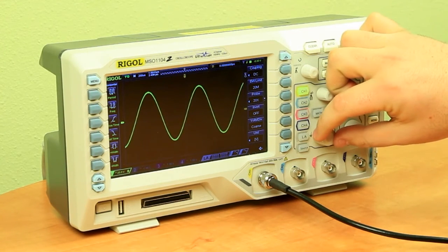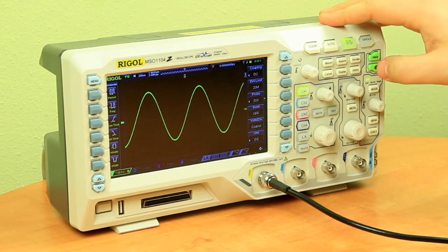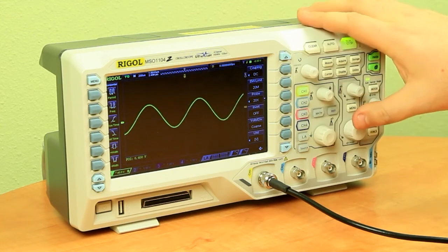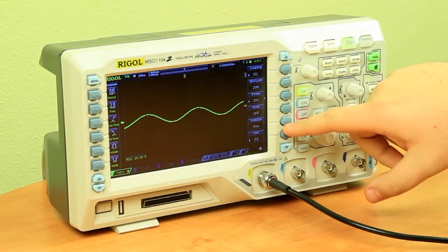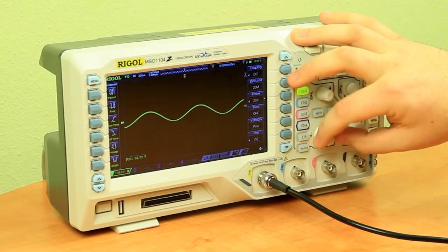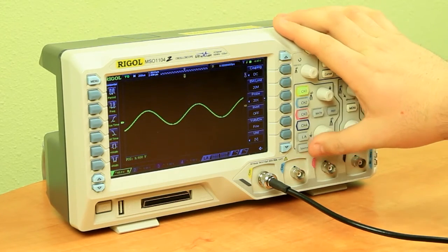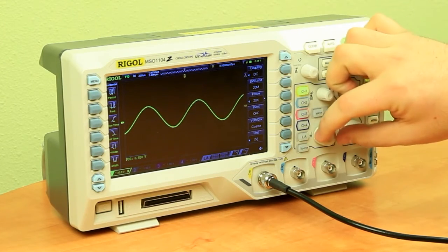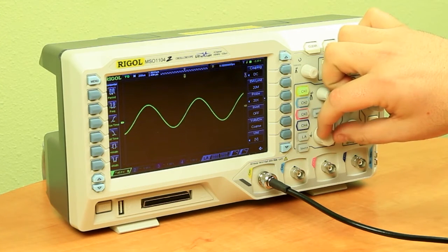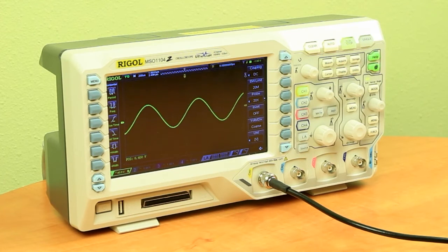Another aspect is we can change the scale of the particular signal by rotating this knob, and we can make it larger or smaller, and then we can also choose between coarse and fine measurements, which are displayed here. So right now we're in fine, so I can make smaller scale changes, and I have to rotate a lot more to get a scale change. Or I can go with coarse options, which are more the presets, which will let us snap in between much larger scale positions. The vertical systems and controls are pretty universal for all of our different oscilloscopes, but they allow you to move around the signal and view the signal as you need.